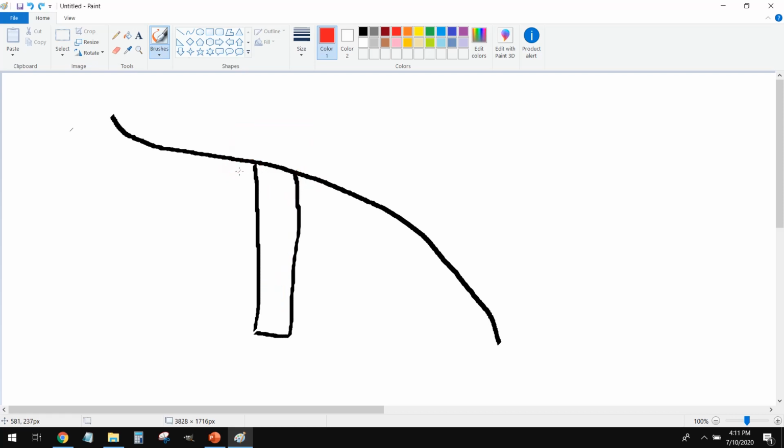So what we do here is we put in what's called a spot face. And a spot face is very similar to a counterbore. However, it's not as deep. And all it's designed to do is to give a flat spot here for that screw to sit so that we can get a full clamping force out of it. So they're typically very shallow, and they're going to sit here just like this, so that this gets full clamping on this curved surface. So you'll occasionally see S-face or spot face on drawings as well.